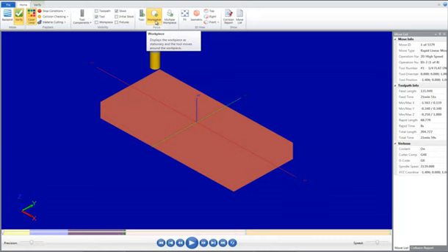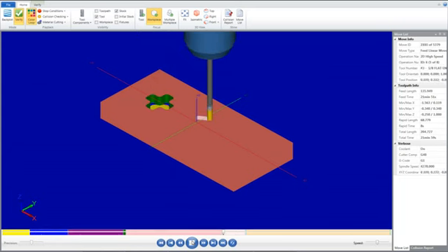As you verify toolpaths, Mastercam displays additional information such as the X, Y, and Z coordinates, the path length, the minimum and maximum coordinates, and the cycle time. It also shows any collisions between the workpiece and the tool. You can now select the Play Simulation button to run Verify. Your part will appear as shown. You can now exit Verify.